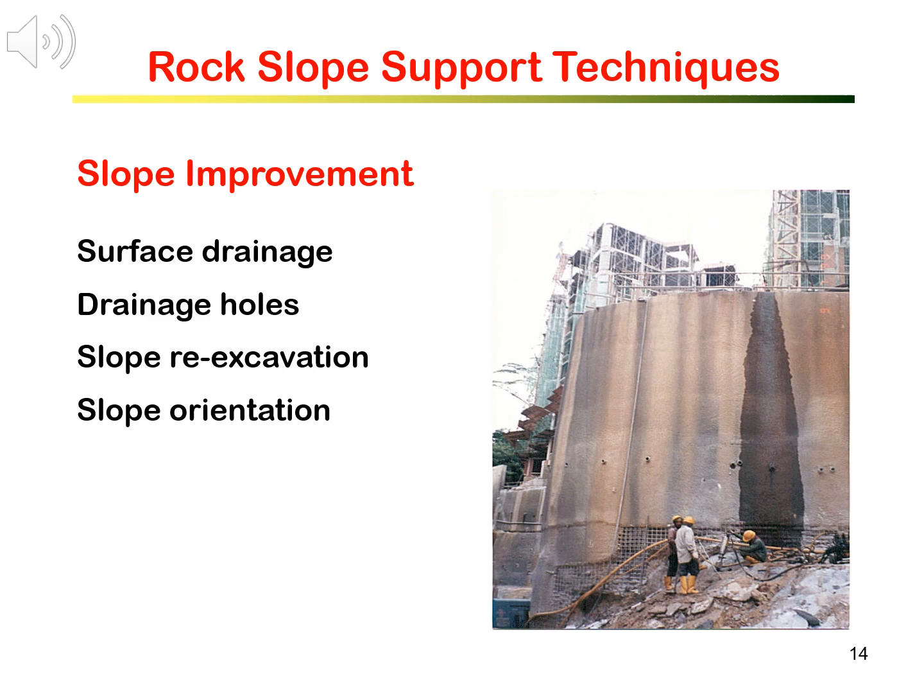The other case is when a major sliding plane is daylighting on a slope. By reducing the slope angle to be similar to or smaller than the sliding plane dip angle, the sliding plane will not be daylighting and the potential of major sliding failure can be avoided. We have learned before that slope orientation in relation to joint and fault orientation is very critical in managing plane and wedge sliding failure. Therefore, optimizing the orientation of the excavated slope can also result in better safety and stability of the slopes.